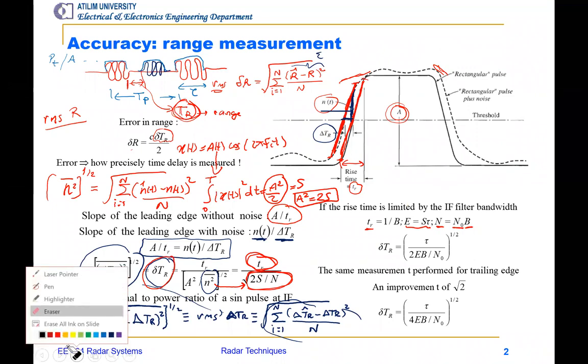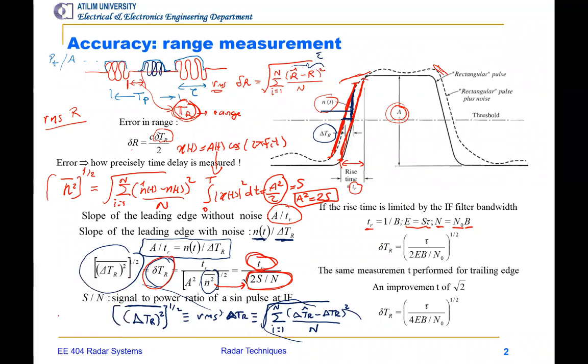the receiver, the radar receiver, how to measure this TR. From the antenna, simply we have an LNA at the radar receiver, we know it, and then a mixer, okay? And then we have an IF stage, which is a filter with an amplifier, we say. The received signal has a frequency, let's say FRF.